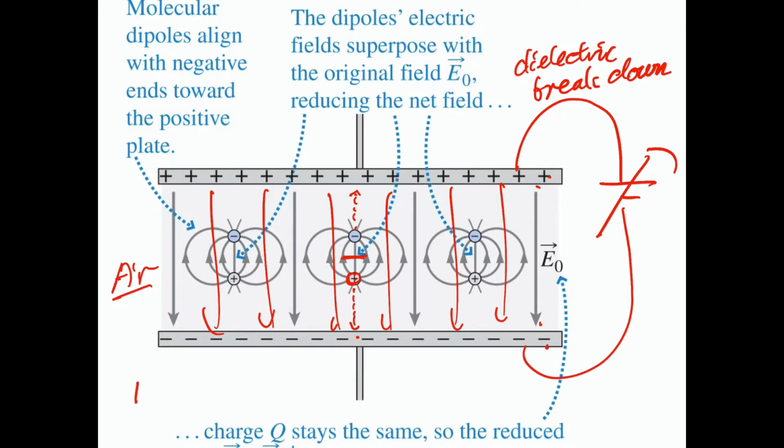Remember, E is delta V over delta X. So there's a maximum here for a specific X. There's a maximum voltage you can put across. Once you go over this voltage, you will break down. You will cause trouble, and this breakdown usually is irreversible. It means once it breaks down, that's it. It damages everything. So you cannot use this capacitor to store energy anymore.